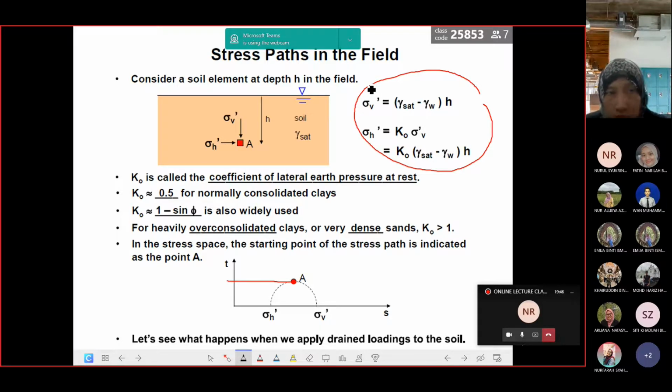Behavior of the soil, apart from getting its results, we want to know the soil's own stress. When we go to the field, we can just take the sample without knowing exactly what stress the soil currently has. We don't know the stress value. What we can know is when we dig out a few samples and bring them to the lab, we conduct experiments such as triaxial, and then we get the stress path that occurs at that site. That's the way, because the stress of the soil at the site in the field we cannot easily find without doing the experimental work.